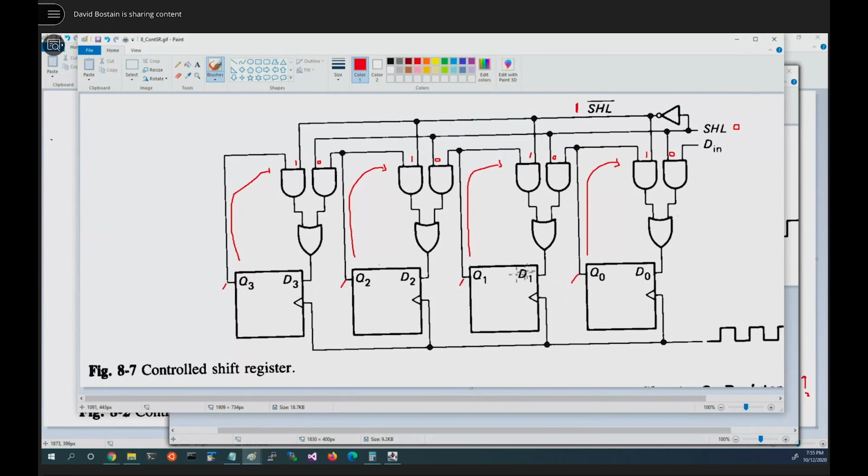And we have some input called DN that we may or may not be ready to shift in yet. So now, whatever Q is decides the result of this AND gate in all three cases. So it's a 1 if Q is a 1, it's a 0 if Q is a 0. In any event, it's the thing fed back to Q, or D, on every clock we see until we change